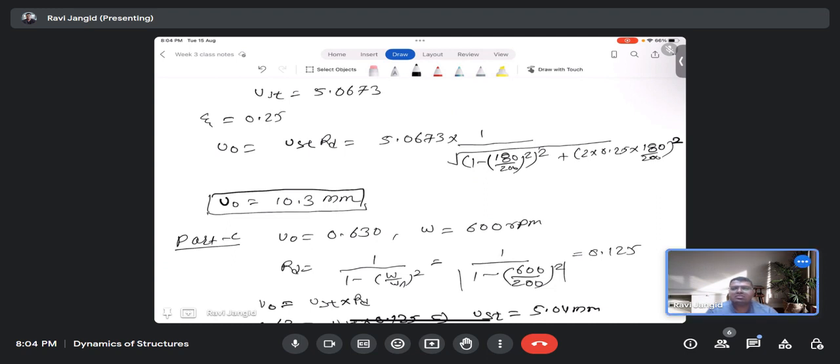While writing this, I write I theta double dot plus damping moment plus stiffness force moment, which is equal to our force F0 sin omega t. While calculating I, I have ml squared by 3 for this rigid bar.